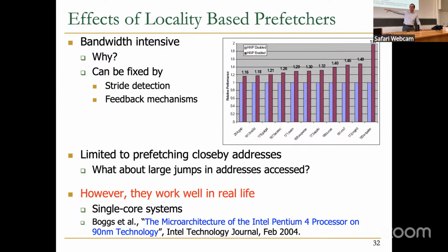What you're doing in the hardware prefetcher is just looking at the access stream coming from that core. If the access stream has some regularity, you'll capture the stride. If the access stream doesn't have regularity, I agree. If you partition your work such that there's no regularity, then you may not get the stride. So certainly partitioning and memory allocation affects the kind of stride that you get.